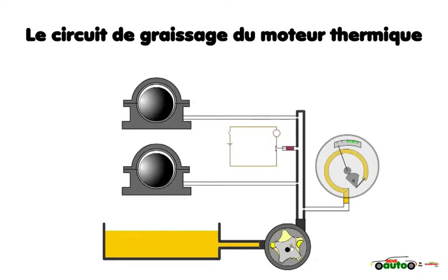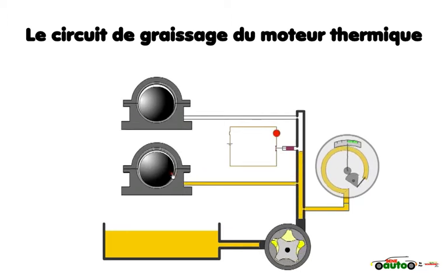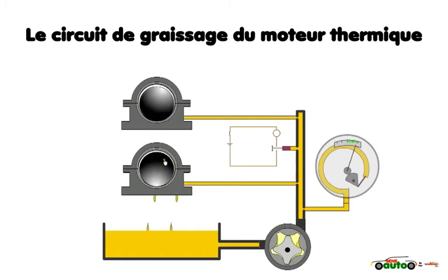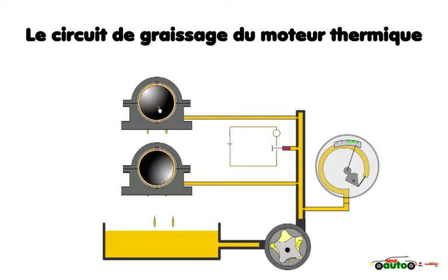In this animation we show a lubrication system, two bearings, a pressure gauge, pressure switch, ignition switch, battery, oil warning light and gerotor oil pump. Again, this is a positive displacement pump. For each revolution, a fixed amount of oil is drawn in and forced through the outlet. When the pump is started, there is an oil flow to the bearings.